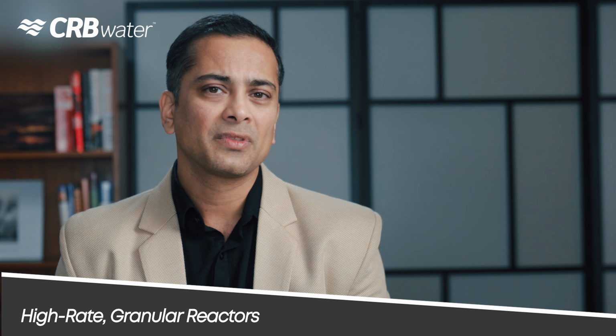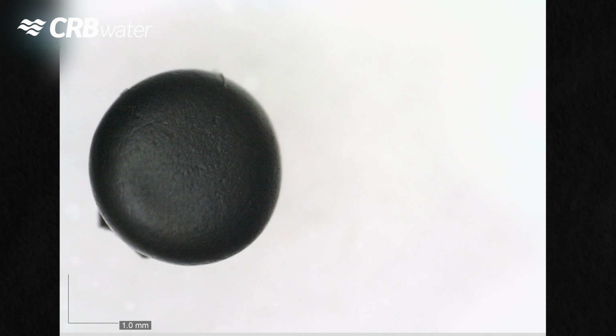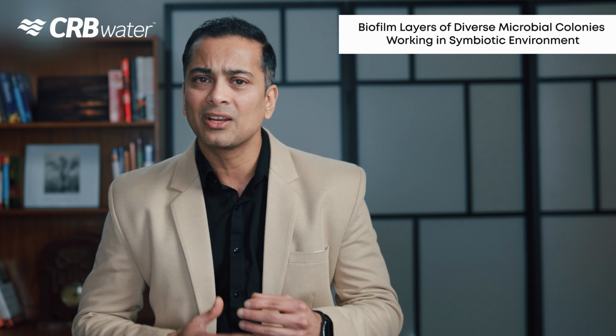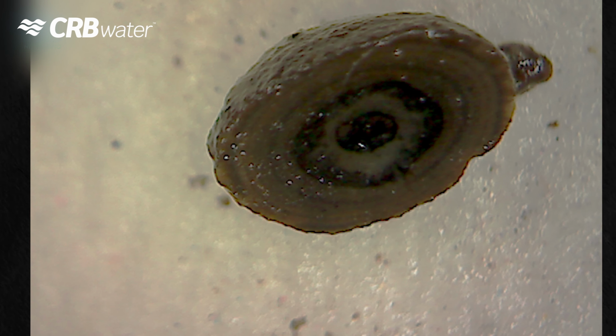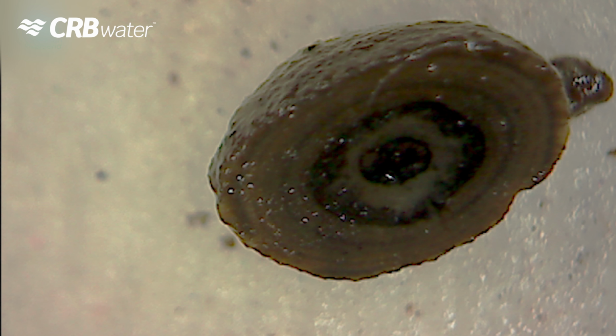Let us start with a brief introduction of high-rate granular anaerobic reactors. High-rate granular anaerobic reactors must generate and retain dense granular biomass to treat waste successfully. This granular biomass comprises biofilm layers consisting of diverse microbial colonies working in a highly symbiotic environment. A cross-section of this anaerobic granule showing different layers of microbial communities is shown here.